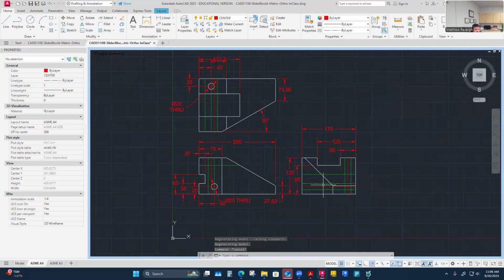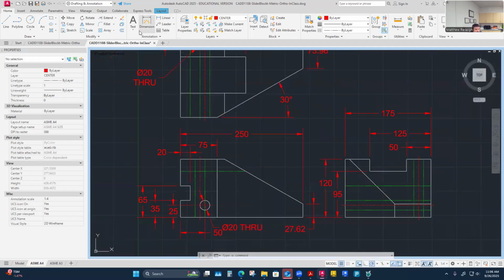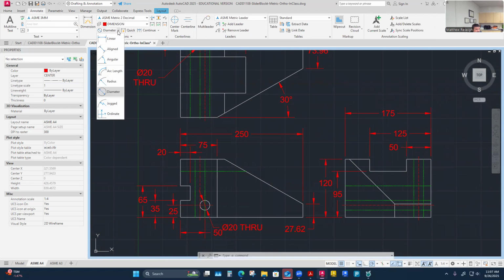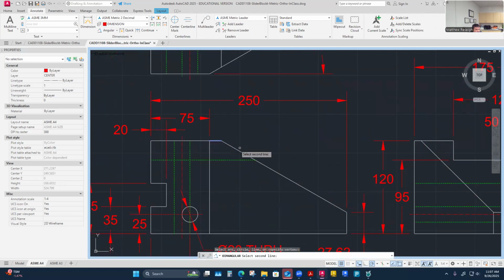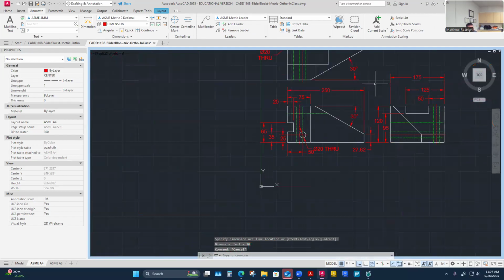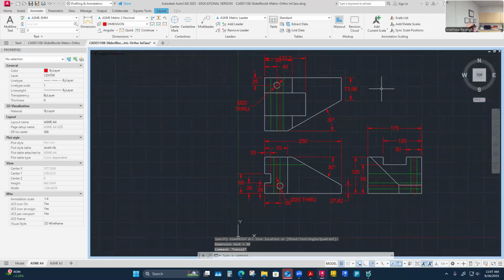I think there's one more that I would probably add, and it would probably be another reference dimension, an angular one. I think the only one I really haven't accounted for is maybe just that nice to know angle from top down, that's why it's definitely a reference dimension. This one maybe. That might be the last one I'd populate here. I just didn't want to miss. They're different 30s, right? One's top down and the other one's from front to back, kind of. So yeah, and they would in the future become absolute reference. Just nice to know is not necessarily, don't base my machine off it.